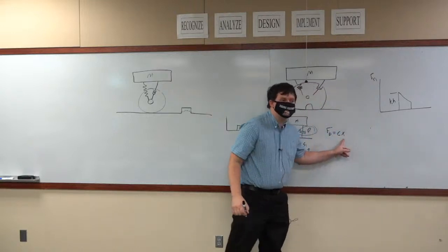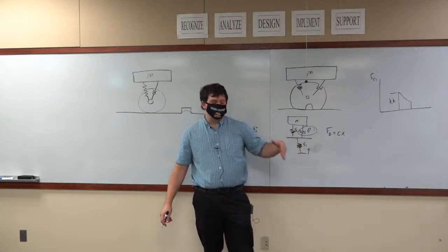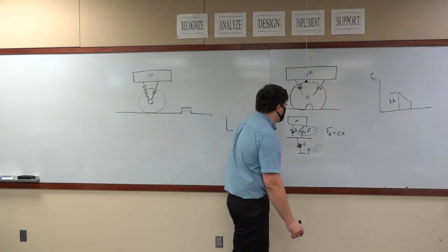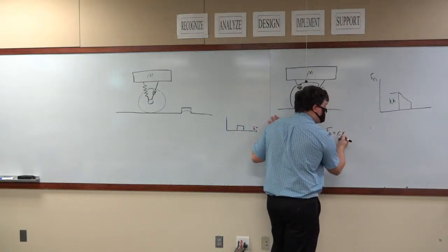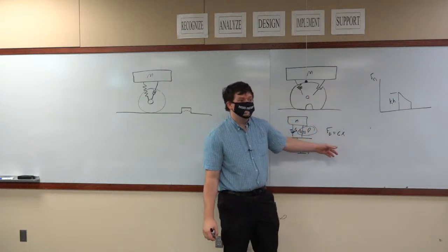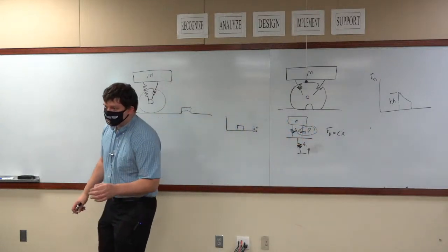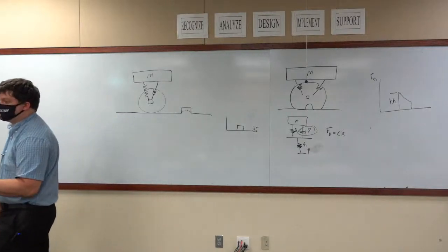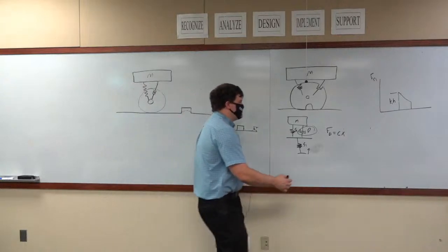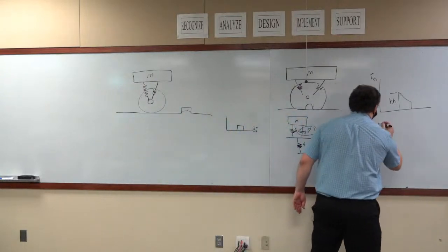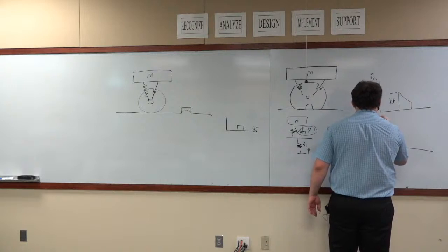If the velocity suddenly reaches infinity, because the vehicle suspension moves upward suddenly, then Fd is equal to infinity too. Your damper prevents your axle from moving instantaneously. You cannot have an infinite velocity, which means your displacement relationship, so we'll talk about displacement of the axle.